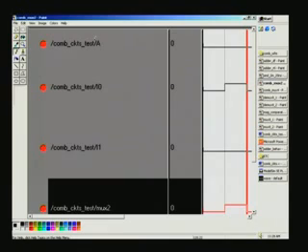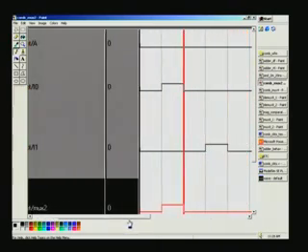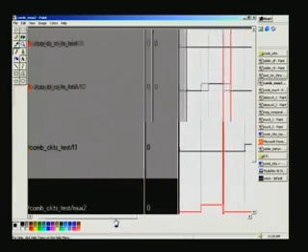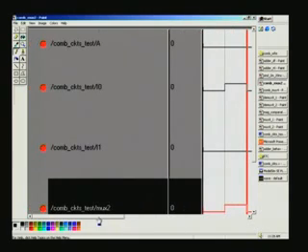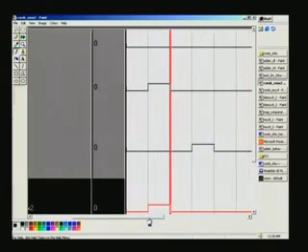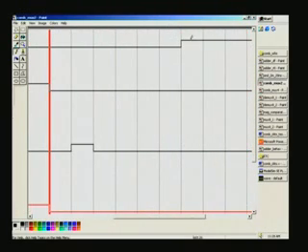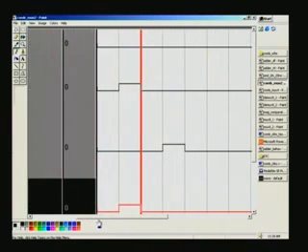And here A is the select control, I0, I1, and mux2 is the output that we have already seen just now. And we will see, remember I0 is the one which will be assigned if A equal to 0, that is what is here, you can see this is 1, this is 0. So all through it is 0 here as far as A input is concerned, which is select input.